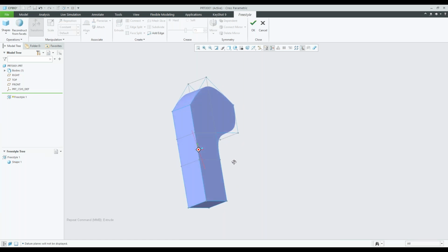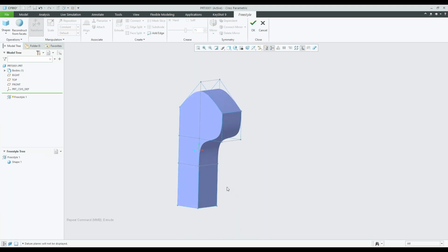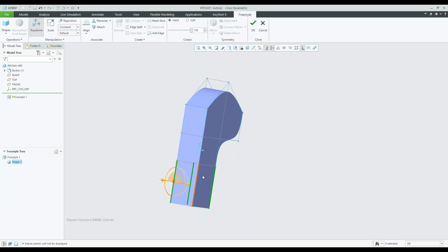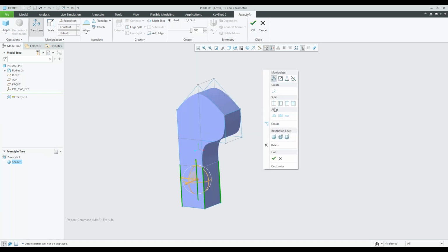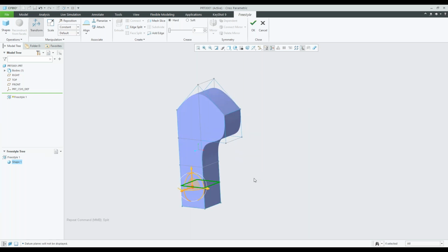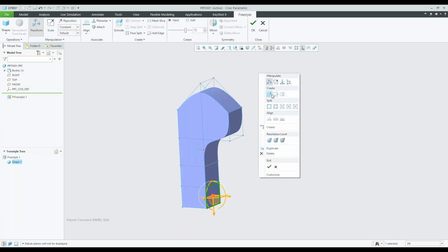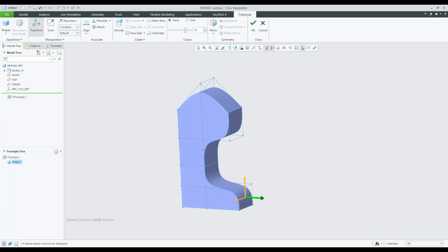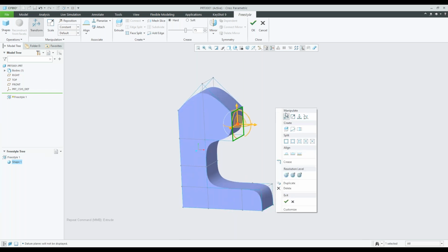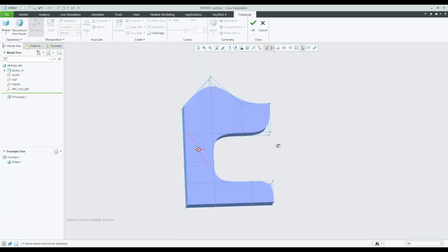You can subdivide edges to add more geometry. So I can grab these edges, right click and split that with one line, and then grab another face and extrude that. All right, let's extrude that once more and extrude this up here. And what's nice about this is once you've done that, let's move these over.